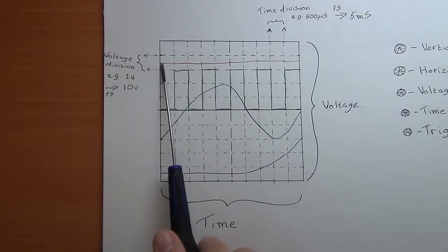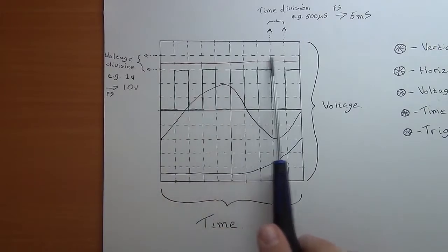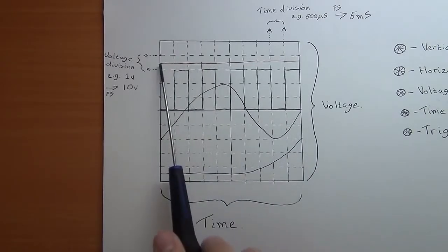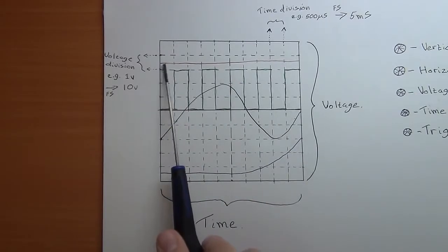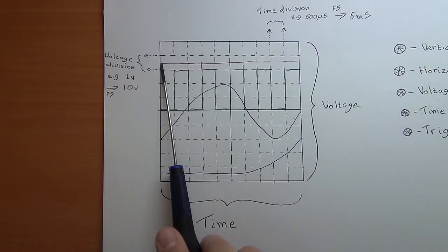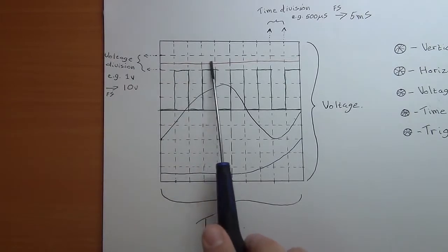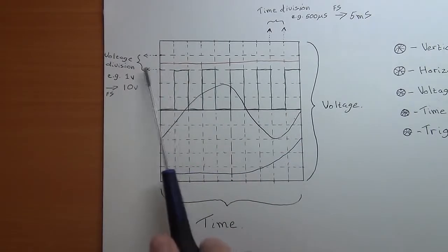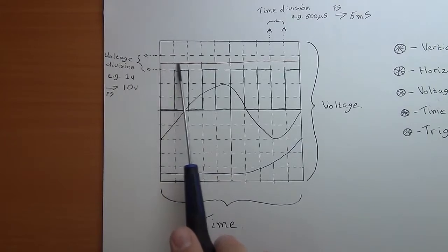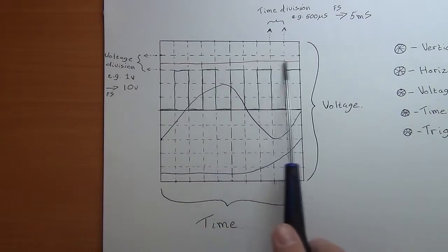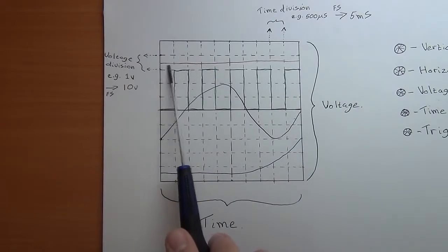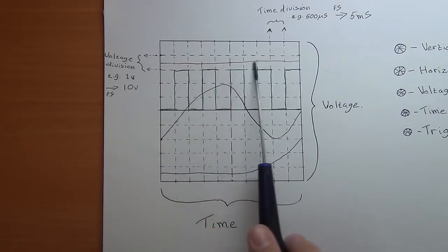The one I wanted to point out, which a digital multimeter can represent very nicely, is a signal at a certain voltage level that stays the same. On an oscilloscope, that's still a signal, but it's going to be represented by a straight line, as this red line represents here. Your level stays the same, it's not changing over time.